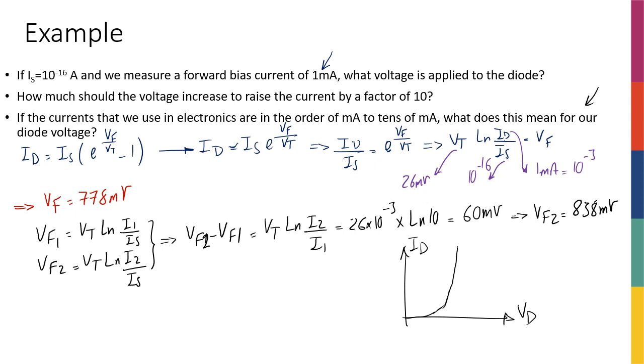So this is a nice sanity check for you guys, that if you're doing any kind of diode circuit analysis and you find the voltage across the diode to be anywhere more than 700-800 millivolts, you have to double check your equations and your calculations. And if you found anything higher than like 850 millivolts, I promise you something is wrong, right? There's definitely something wrong in your calculation. You have to actually go and find it.